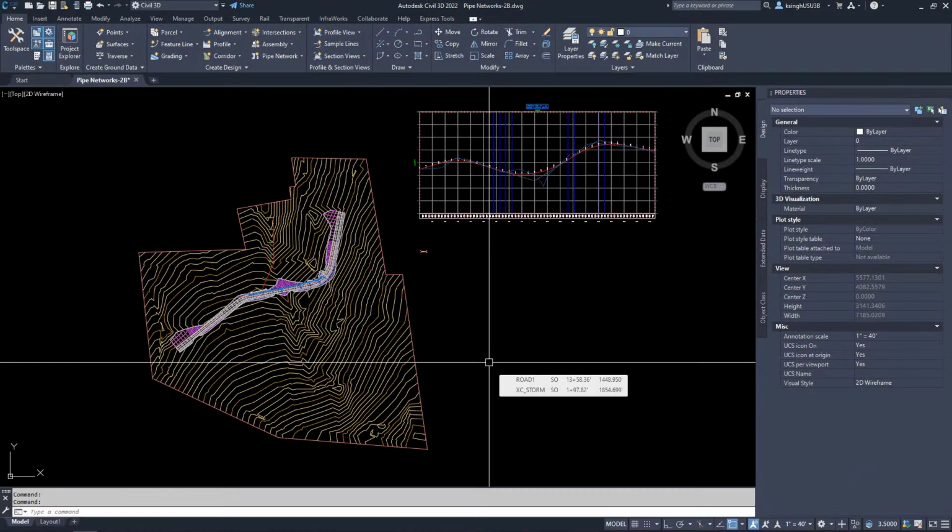In this exercise, you'll add a branch to the existing pipe network layout and use the part status to review and edit the layout. In addition to indicator icons that indicate where parts can be connected, you'll see icons when the pipe or structure you're adding to the network will break an existing pipe. The pipes created by the break are automatically connected to the new structure or pipe.